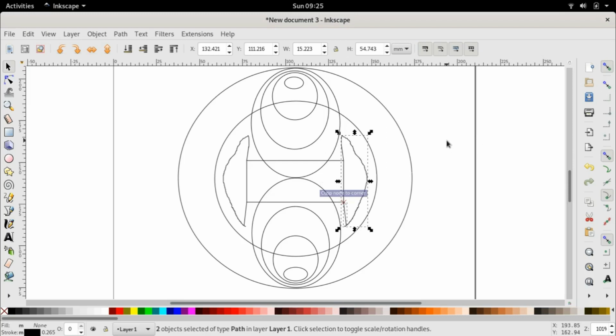Right? So such a rotor is called a salient pole rotor, because now instead of having a cylinder, we have only so many poles as we have designed. Now so far we are talking about a 2-pole machine. Later on we can talk about multiple pole machines such as 4-pole machines or 6-pole machines. But if we have a 2-pole machine, then we have 2 salient poles diametrically opposite each other. And as you can see, there is a huge air gap in the other parts.